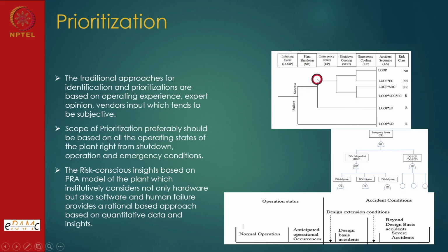So we will choose this event tree and see what the core damage frequency is, and then we will come to the fault tree level. Let us say it was related to emergency power. The modification was related to power supply. So we had two diesel generators, three diesel generators here, and there is a common cause thing also. So was the modification related to common cause?